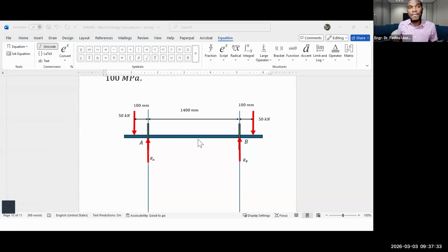Then the next force available for us is the second 50 kilonewtons, right? And that acts at a distance of 1,500 millimeters. But when we check the line of action, if we pivot the system at point A, then this force will tend to move this system in this direction, which is the same direction as your second hand of a clock or watch moves. So that is a clockwise direction, and so that value there will be positive.